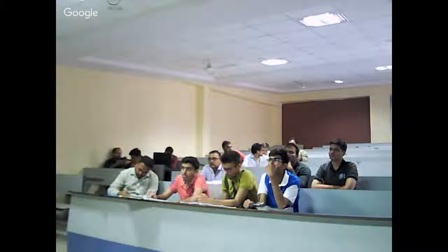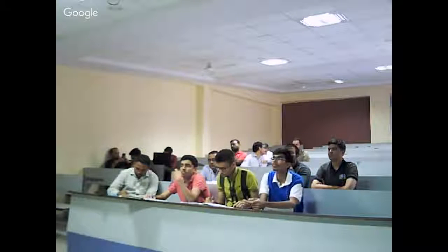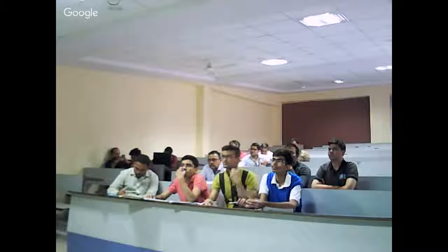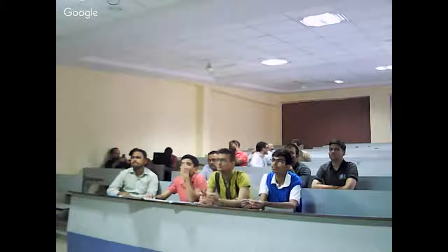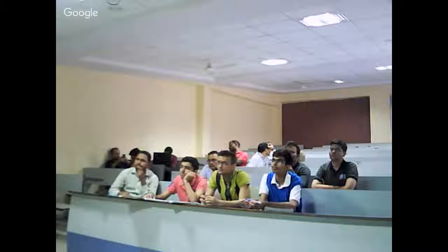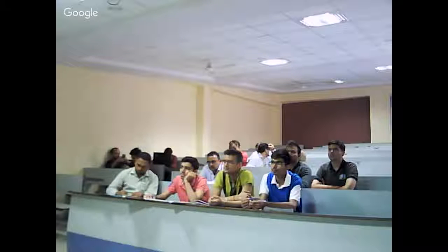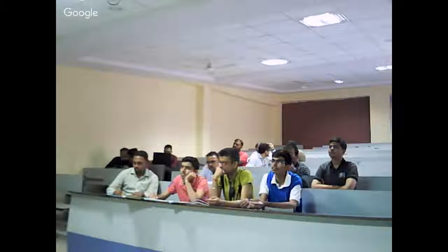Now, for this particular robot, this is the interface software which can be used to control and program the robot. What you are seeing on the screenshot is the interface of the software: the title bar, the menu bar, the toolbar. At the bottom, you see two windows, a manual movement window and a teach position window. The manual movement window is like a teach window. When the software is in control, from here we can select individual joints. You can see here the joints option as well as the XYZ option.